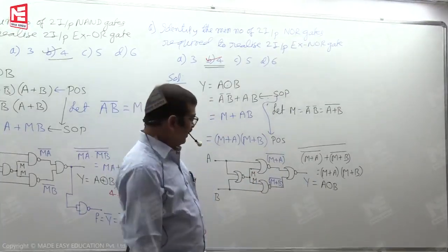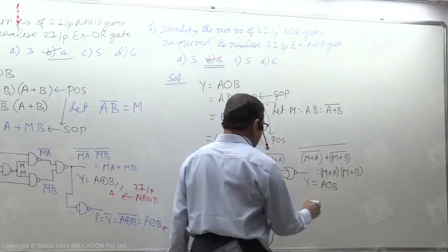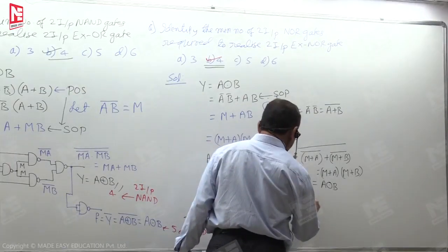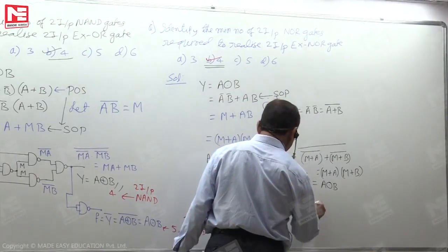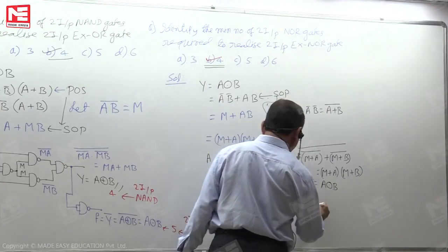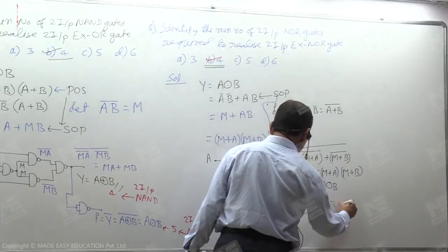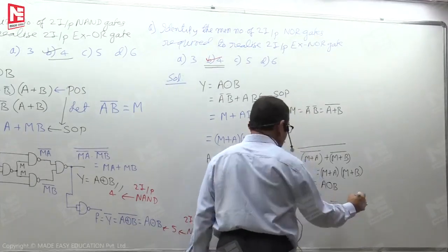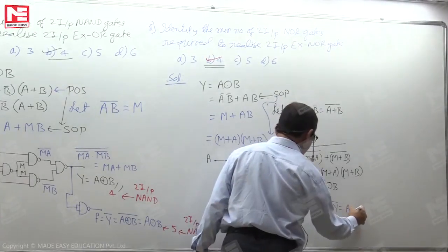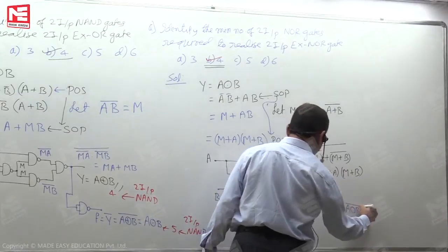If you try this for exclusive OR operation, using the minimum number of 2-input NOR gates, we want the exclusive OR operation. It is possible for us to say now: for complementation purpose, we need one more gate. This gate output we want to read as Y complement. It means we want to have A XNOR B complement.